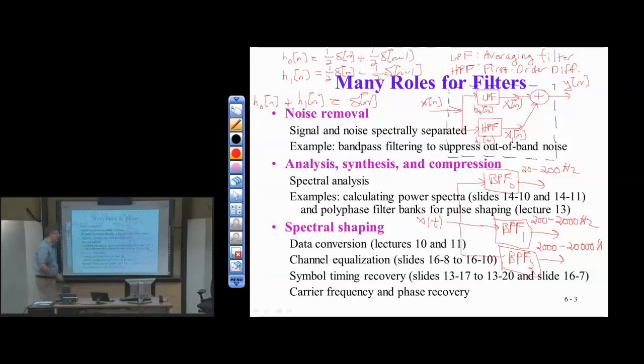Now you could have more than 3 in your speaker box. You could have 5, you could have 2. But anyway, the decomposition is to get us in the right range to then feed. There are 2 reasons we do this decomposition. One is we can apply a different power amplification on each band of frequencies. And second, if we design the filters just right, we can get their impulse responses to actually add up to 1.